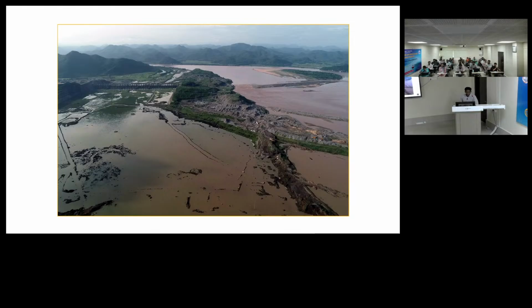Can anybody tell what dam project this is? This is the Polavaram dam. You can see the length of the dam. The discharge was so high. Earlier it was just a hill, but here the depth of the overburden is up to 80 meters. The rock is not available even up to 80 meters, so the only option is to construct an earthen dam. So the main dam portion they are constructing as an earthen dam.